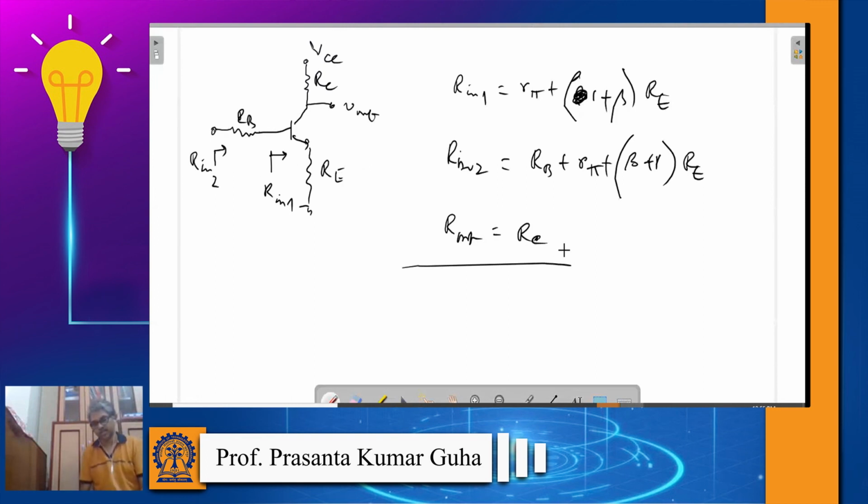Ultimately you need to have biasing along with the AC signal which you want to amplify, because biasing will ensure your Q point that we have mentioned already. But so far in our calculation we haven't considered those resistors, R1, R2, Thevenin voltage, Thevenin resistance and all that. So in the next class we will consider that and find out the gain again, and we will see whether the gain changes because of single resistor biasing or voltage divider biasing. We will consider those things.